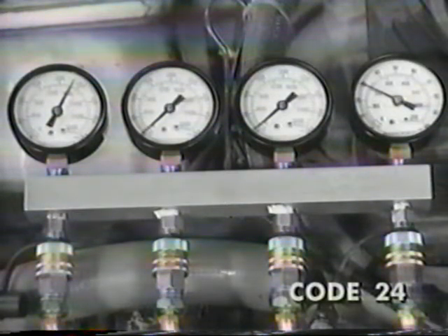The main pressure should be 225 to 255 psi or 1550 to 1760 kPa. Interrupt pressure should be 0, and the bypass lockup pressure should be 0, and lube pressure should be 20 to 35 psi or 138 to 241 kPa. If any of the pressures are out of spec, inspect and clean the oil pickup tube and strainer in the oil pan. If they're clean and intact, replace the hydraulic valve.